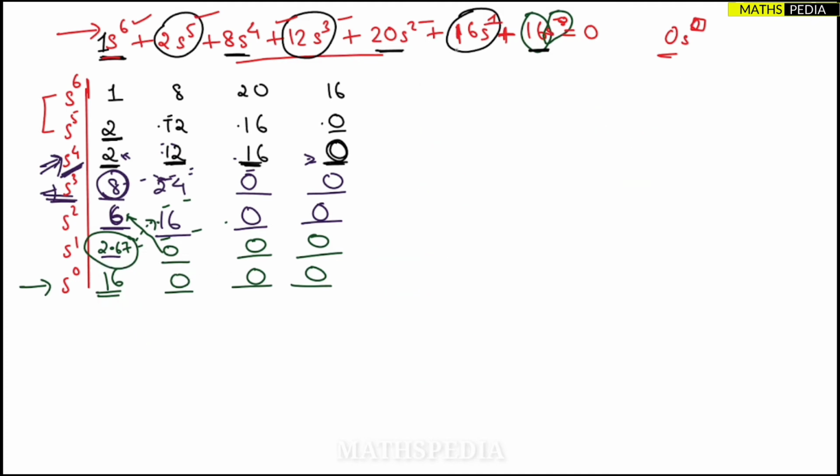Now here we observe that there is no sign change. That means from the first column, you have to always see the first column of the Routh's array. We can see there is no sign change. Correct? Because all the signs of the elements we have found are positive. Positive 1, positive 2, 8. There is no sign change, so the system may be stable. We are not sure.